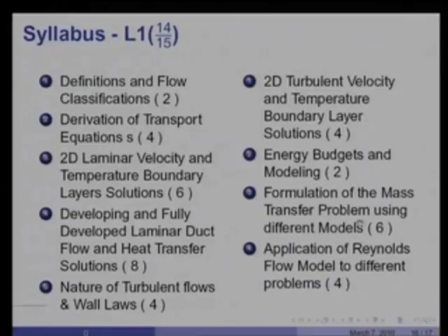These sub-models essentially depend on the postulate of analogy between heat transfer and mass transfer. But it is very important to understand the nuances that are involved in this formulation of sub-models. Out of this, I will pick one model called the Reynolds flow model and show how well it applies to practical problems involving mass transfer.